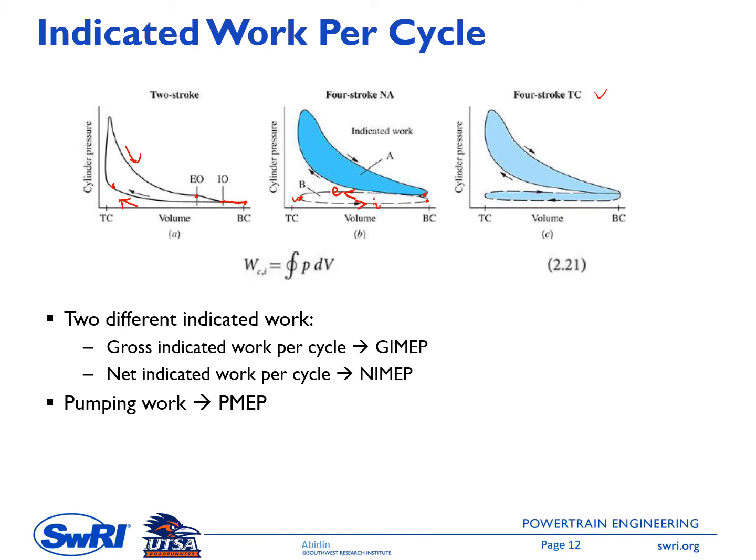The main important thing here is that the intake pressure is lower than the exhaust stroke pressure. Because of this condition, there will be a negative work. You can see that the process line arrow direction is counterclockwise.